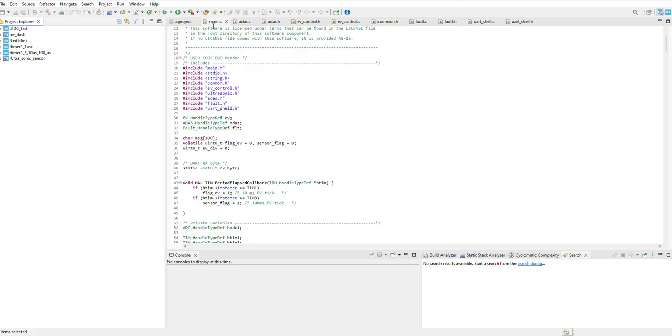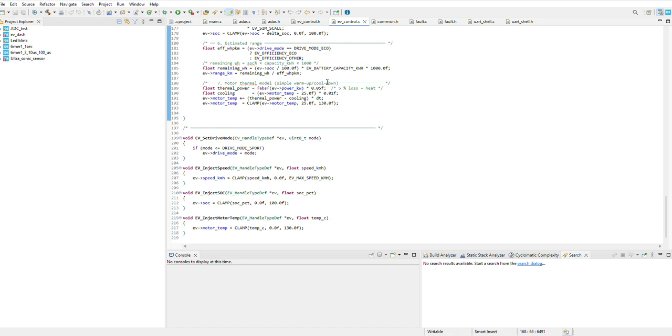Yeah, many header files and source files are there to keep it modular. Then main.c. Here initialization of STM32 peripherals is done using UART and GPIO. Sensor values are processed and transmitted through UART. Then evcontrol.c module is responsible for EV parameters, torque, battery charge, and motor temperature. Then ultrasonic.c handles the three HC-SR04 ultrasonic sensors for detection in front, left, and right.